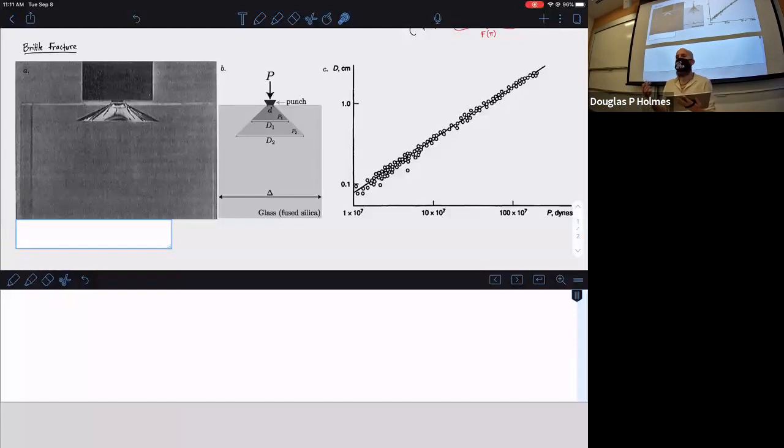Well, the nonlinearity in a fracture problem is that usually you think of elasticity as giving you a set of boundary value problems. You have some set of equations, you have some known boundaries in which you're going to apply forces or displacements, and then you're going to solve to determine either what the stress is in the material, or what the displacement of the structure is, depending on what you're interested in. The problem is that in fracture problems, there exist more boundaries than we're thinking of.